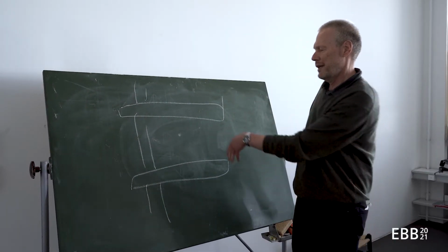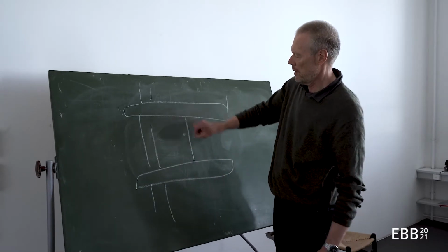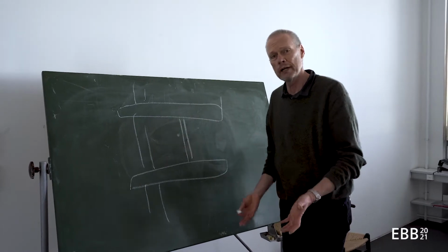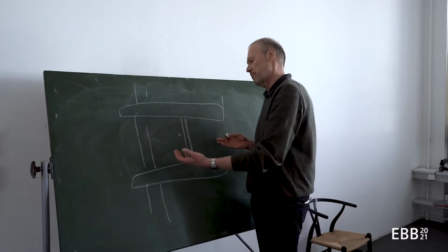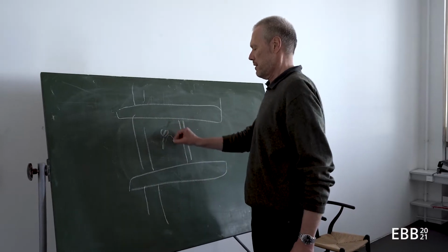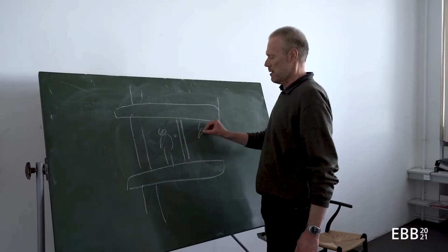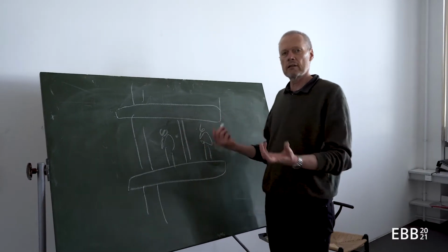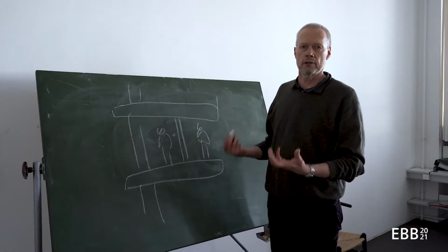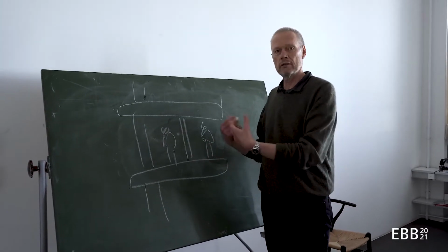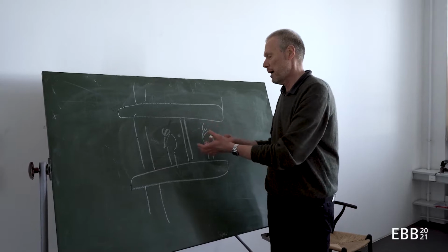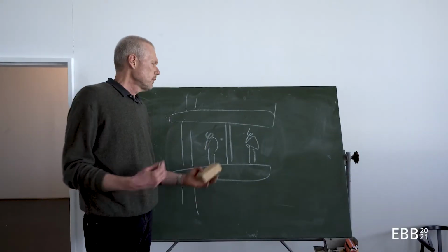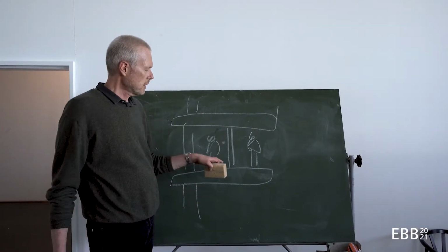And now I want to create a separation between one part and the other. And these walls here are non-load bearing, but they are separating this space here from this space. They might be acoustic or they might be visual, so everything depends on what my demands are in terms of performance of this interior wall. So I have different solutions for this type of wall.